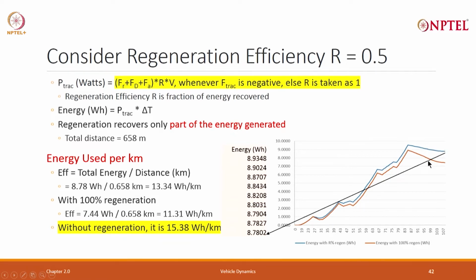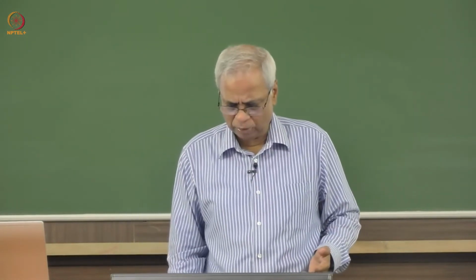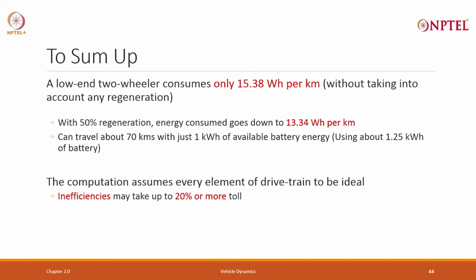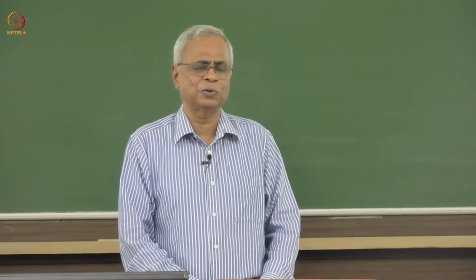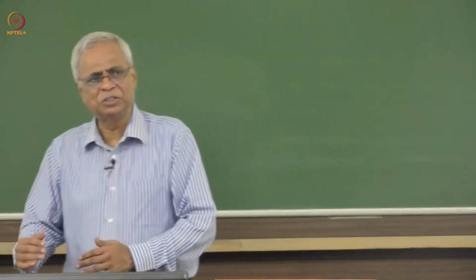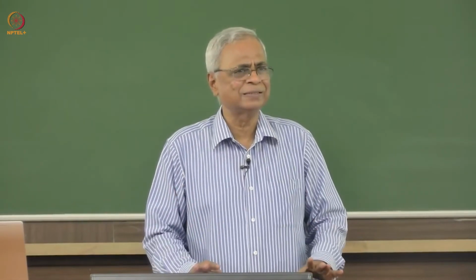We can now change the regeneration to be 30% or 10% or even nothing, and we are able to compute the energy per kilometer in every single case. All right. This is something that we did for the two-wheeler. So, we essentially have got the hang of it. Why did we do individual forces? Why did we look at the total traction force? Why did we look at the total torque, the total power and energy? Now, combined with a drive cycle, we are able to figure out what it takes, what is the energy that it takes.